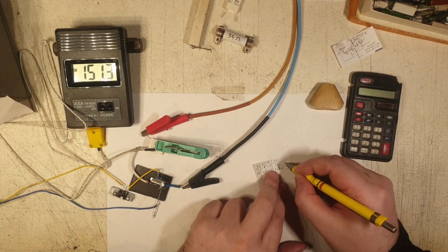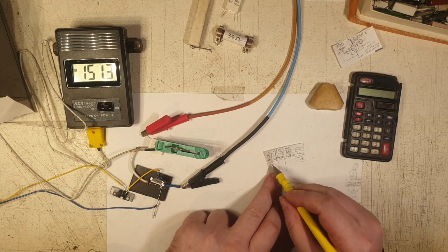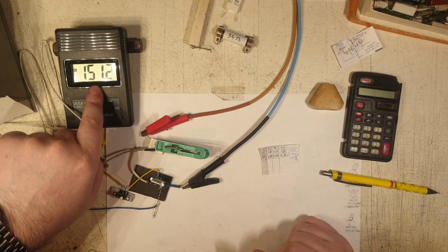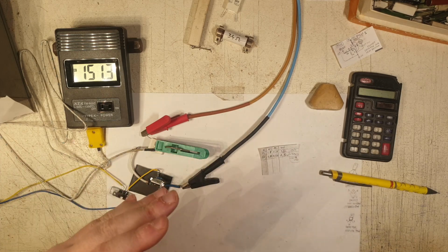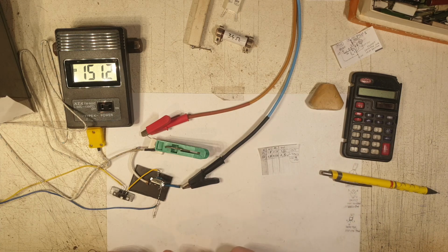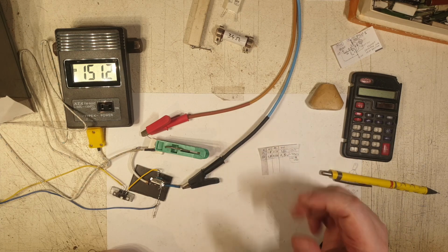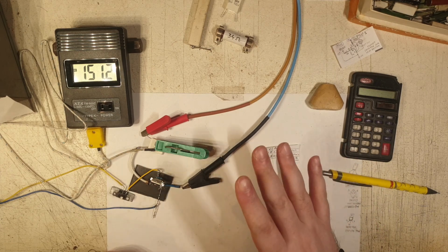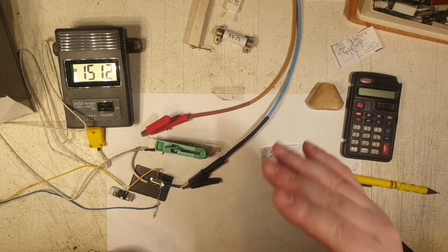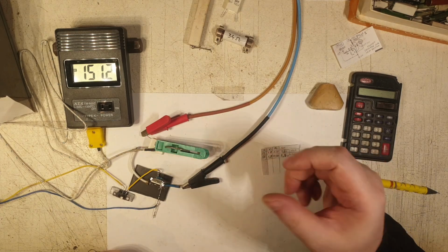In about 40 minutes of testing, the temperature is 150 degrees Celsius over the resistor load that I'm having there. This 10 ohm resistor. Yeah, fantastic. I really like it. But what I don't like is this extreme temperature that I'm getting. This is an extreme temperature, at least for my way of doing things. My policy about driving components, no matter what the component is, even if it's a resistor or transistor or a switch, whatever component it is, you should not get more than 50 degrees Celsius from that component running. It should run at cold temperature, at ambient temperature, or a tiny little bit over ambient, but not too extreme, not too hot. And this is too hot, way too hot. It's 3 times my rule of 50.